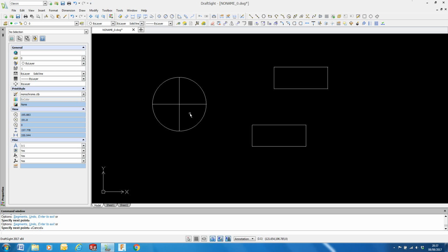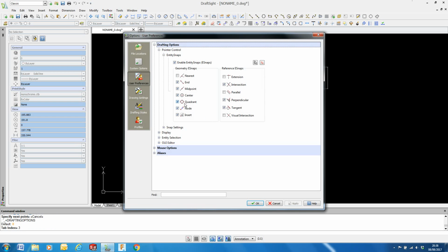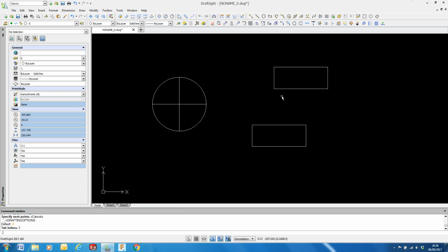If we draw those 2 lines in, as I have, you achieve 4 quadrants. You've split that circle into 4 pieces, and those are your 4 quadrants of a circle. You can go and study your geometry, get your geometry books out, or type that into a search engine. Those are your 4 quadrants, and those 4 points are your quadrant points. And if we go down to our snap settings, I'm just hovering over there to show you Esnap. If you recall, right click, settings, and you will note I have the quadrant points turned on. I can snap to quadrant, I can snap to center, I could snap to the tangent point of a circle.